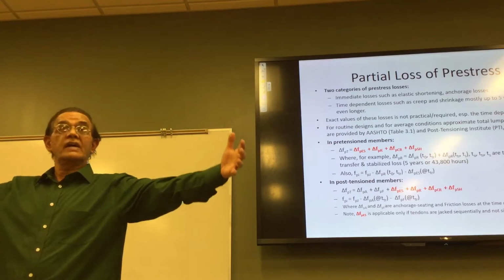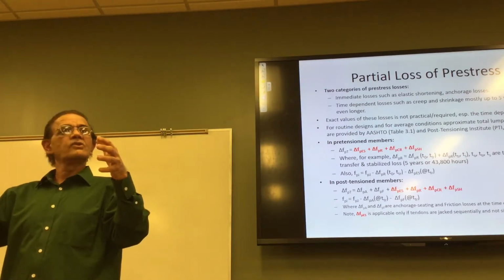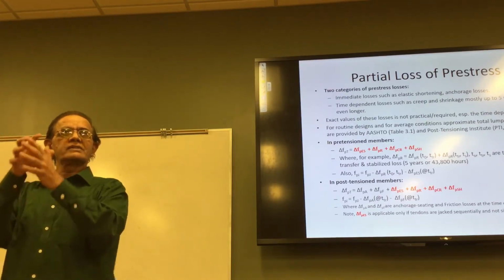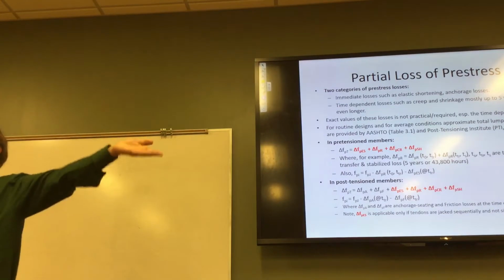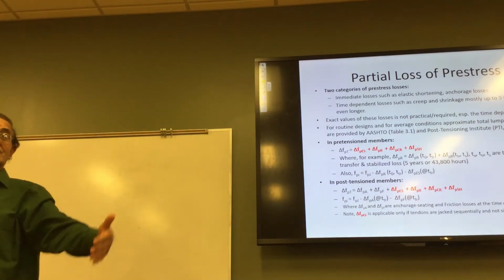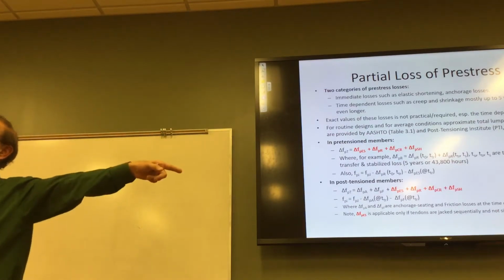So in other words, you got 100 kips here, 100,000 pounds. As you go inward, you're going to lose some more, and some more, and some more. And there are procedures where you're pulling only on one side, not the other side, because the other side is blind. So you're pulling on one side, now you got maximum loss on the opposite end, right?